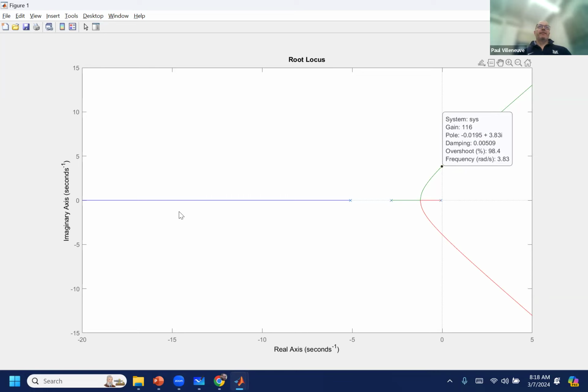Because I think you can understand that when you add K on top of the K above, if you put in K above 120, already it's unstable. But then I'm thinking, how would you have a stable system with K on the other side? It makes sense. The poles would be in the right-hand half plane. If you put in K above 120, then the graph is unstable. Correct. But then here on the side, the gain is above 120.